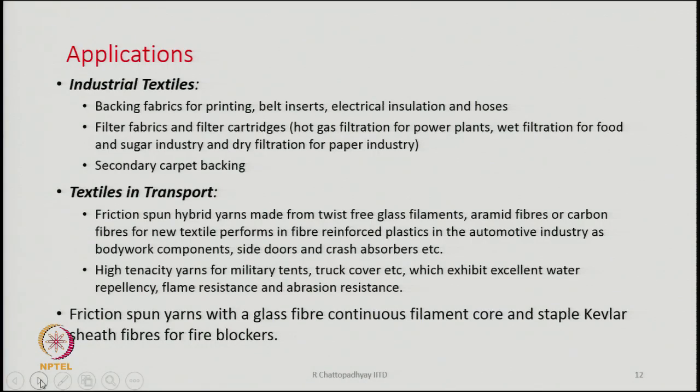We can also spin core spun yarn on ring spinning technology, that is possible. Here also we can spin core spun, but we can then wrap it better, wrapping it by not just one type of fiber, but different types of fibers also. If we need different fibers and different layers, we can wrap it by different fibers, different layers. Introducing a filament is much easier. We can introduce not just one filament, we can introduce multiple filaments. Filaments of 2 types also can be introduced simultaneously. So, flexibility is more, and therefore, industrial applications are more.